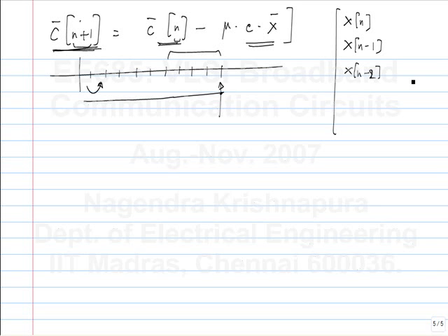So this is typically what is done. This is mainly also to save digital power, because if you have a long equalizer, in fact in some cases you can have very long equalizers, like for the gigabit Ethernet cards, the equalizer in that has of the order of 100 taps, 200 taps, and so on. So basically each of these coefficients has 200 elements, and you have to update that. If you want to update it in every cycle, that's a huge amount of power. You certainly don't want to dissipate that much power. So you slow down the adaptation. And it works well enough because adaptation anyway is required to track out the slow variation.